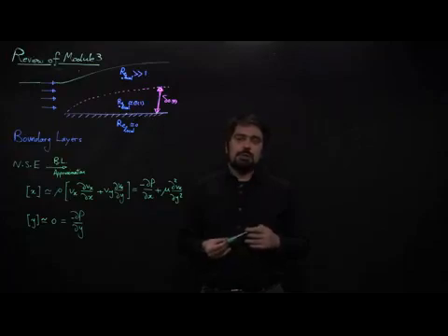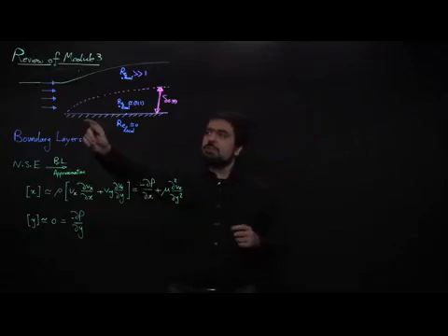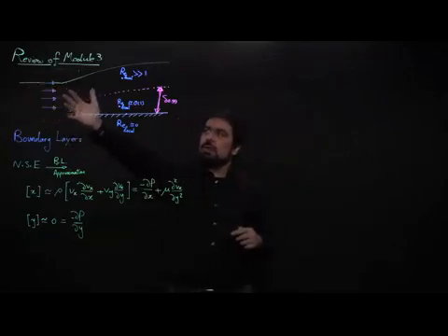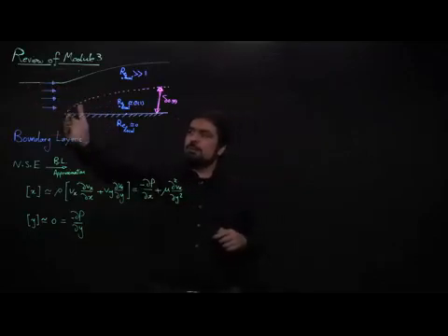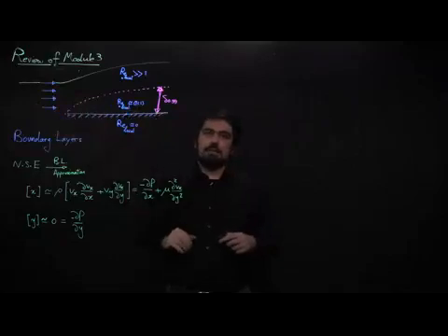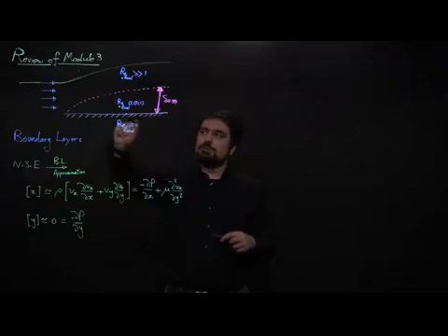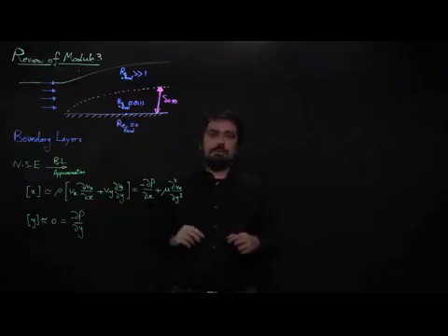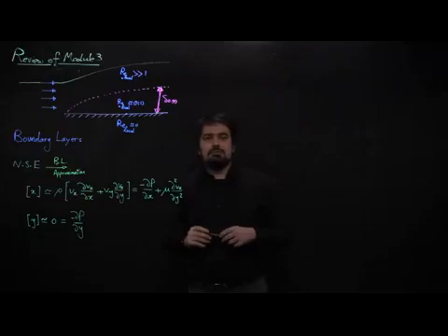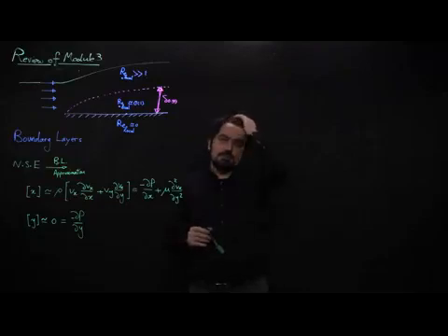The boundary condition that we got rid of was the no-slip boundary condition. But in reality, the no-slip boundary condition is important. For example, you have a uniform flow from infinity approaching a flat plate that starts from this point. Fluid elements very close to this wall, to this flat plate, will have exactly a velocity equal to 0. That's the no-slip boundary condition.